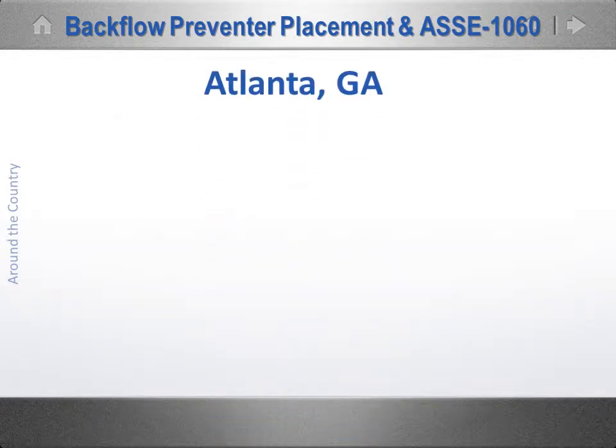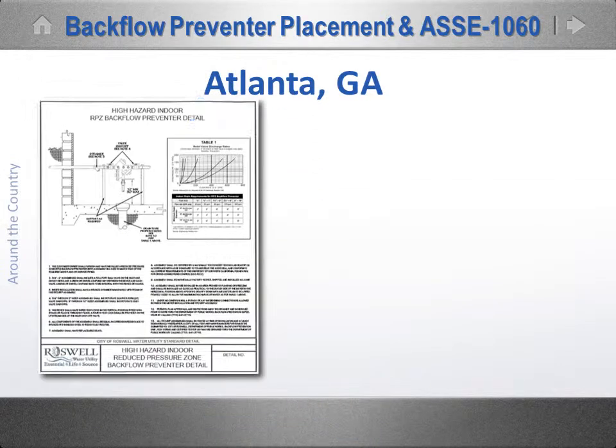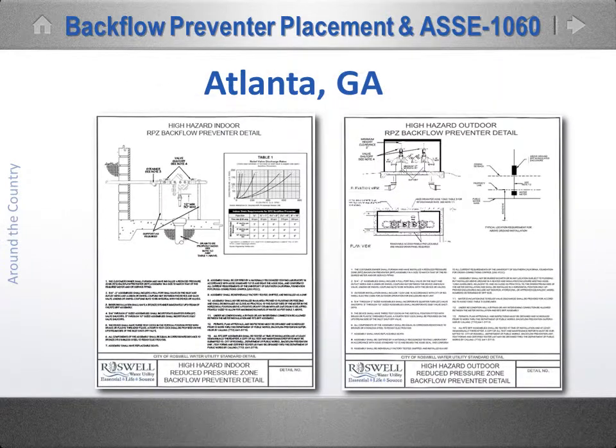Within our Atlanta watch list, Roswell, Georgia is an Atlanta suburb of 200,000 people in Fulton County. Because legacy methods die slowly, last summer they articulated a very smart middle ground position for getting backflow preventers out of harm's way. Recognizing that drain capacities for small-sized RPZs can be accommodated with a typical 4-inch drain system, they detailed 2 methods of RPZ placement, one indoors for small RPZs and one outdoors for larger sizes.